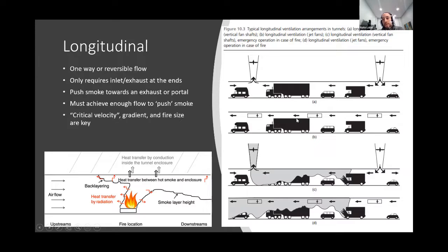So in a road tunnel, particularly a road tunnel with one direction of traffic in that tunnel, the most common solution is that in a fire mode, you blow the smoke in the direction of traffic. Because the idea being that these vehicles ahead of the fire can continue to drive out, and then the vehicles behind should not be affected by smoke.